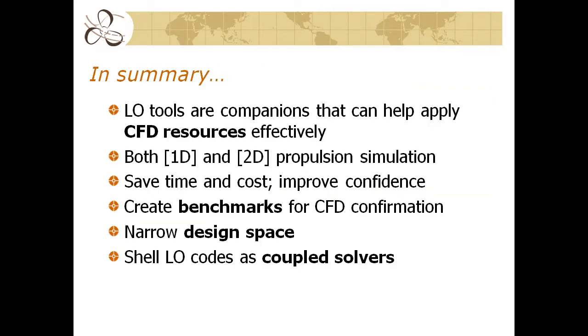So in summary of what we have described and talked about here today, lower order tools are, for me, not only important, but absolutely critical and crucial to successful design, because the important work is done early in the design, in those stages where we don't know enough about the ship or the propulsor to really justify higher order codes. But when we get to that point that we do, we will have set the table with the 1D and 2D methods, so we can have benchmarks to know what successful outcomes from CFD are going to be, that we've narrowed the design space so we're only dealing in the neighborhood that we know we're going to find our best design, and that we can couple that with things like Excel or other solvers to very quickly achieve those things.